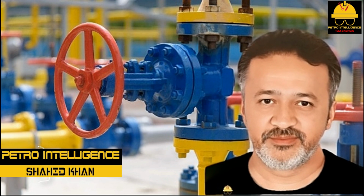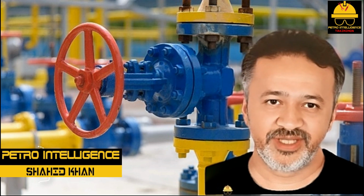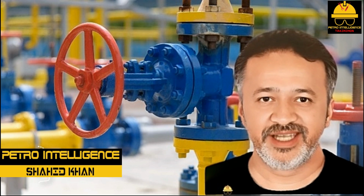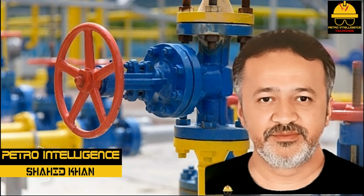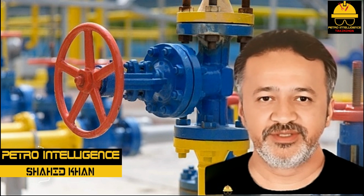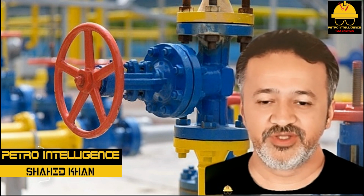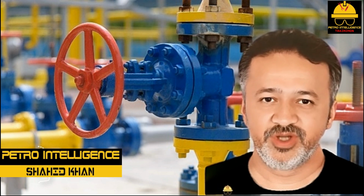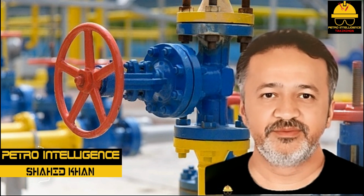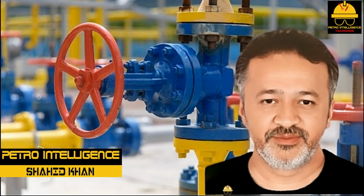Safety valves. Safety valves are considered to be a process system's last line of defense. They are designed to respond quickly to excess vapor or gas pressures. When a system overpressures, safety valves respond to allow excess pressure to be vented to the flare header or to the atmosphere. This venting prevents damage to equipment and personnel. This type of valve is very similar in design to a relief valve.